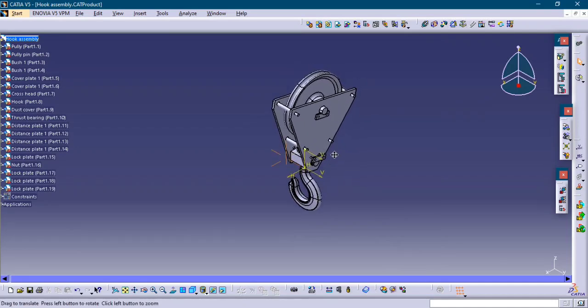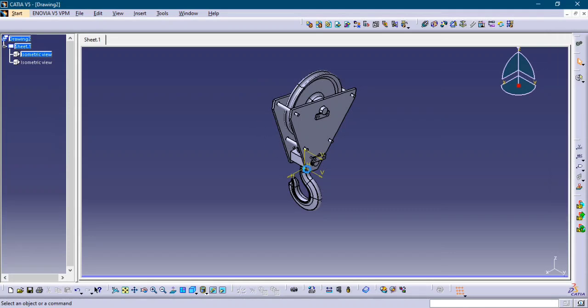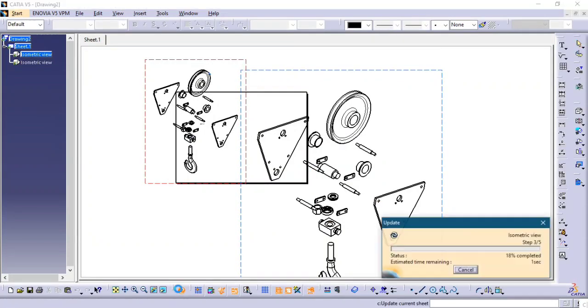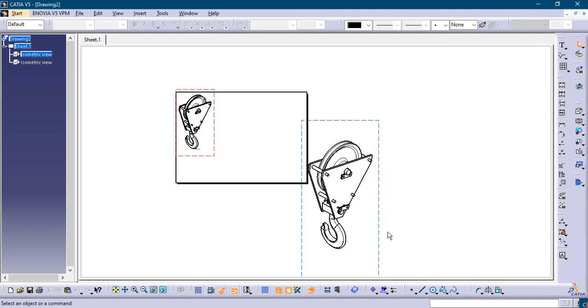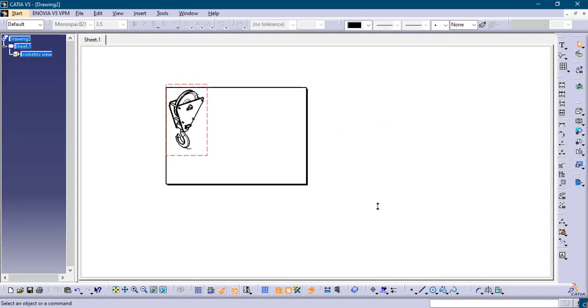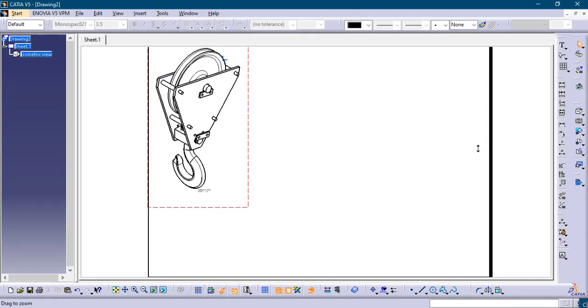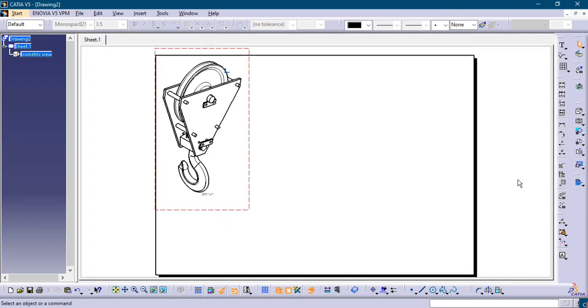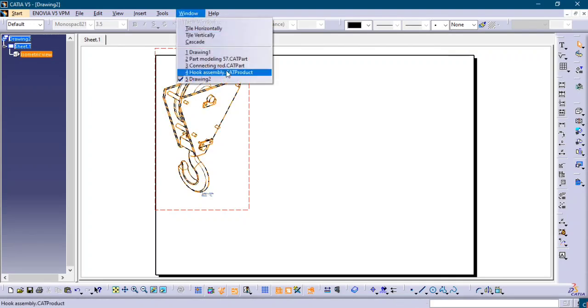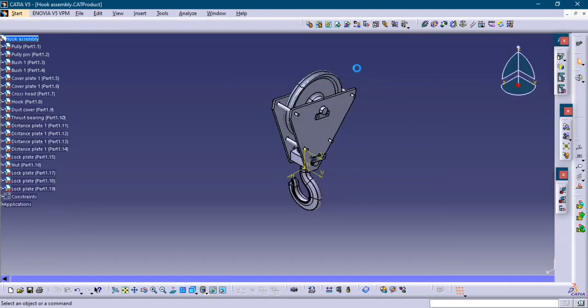How do you create scenes? I will show you that now. Click on window and assembly. Here is our assembly part, and here you can see the scene option. Click on this scene and set it to full. Click on OK. Now here is a green background, that means you are in the scene environment. Anything you do here won't impact your design object. The explode tool is there, so you can explode all things. Click on OK. Now things are exploded like what you did previously.